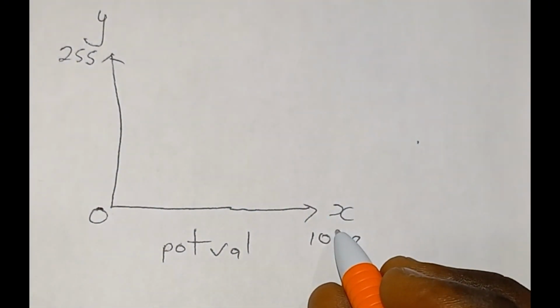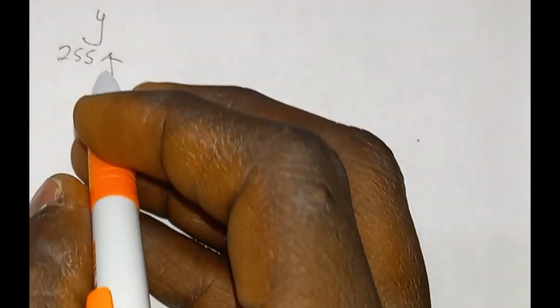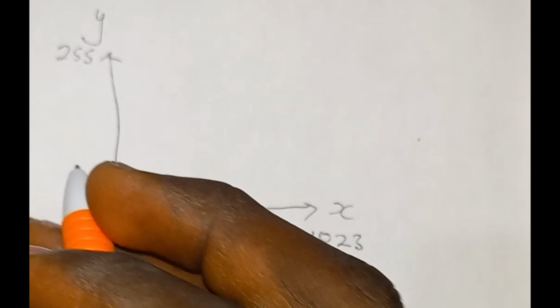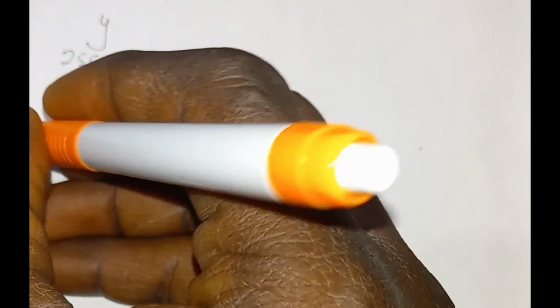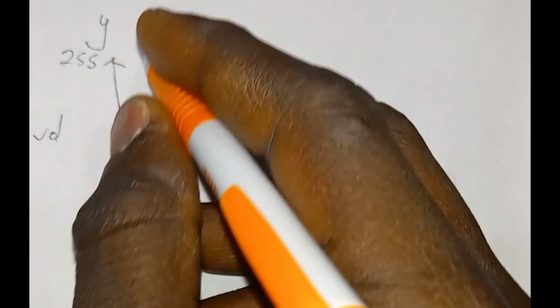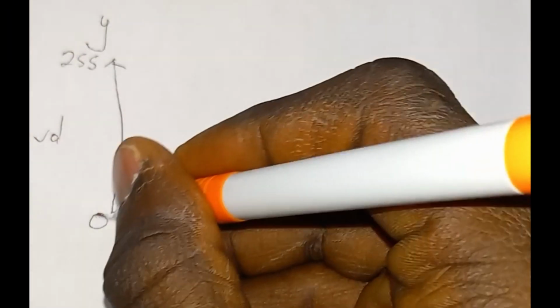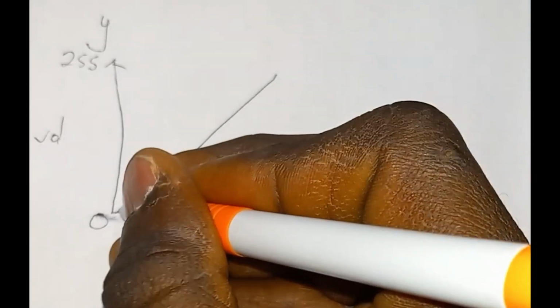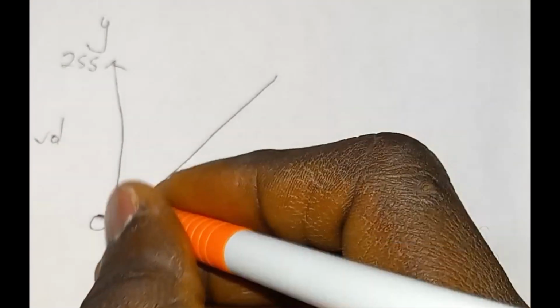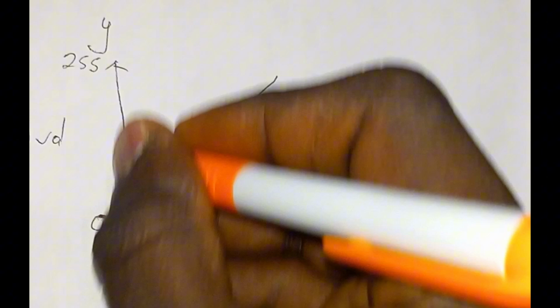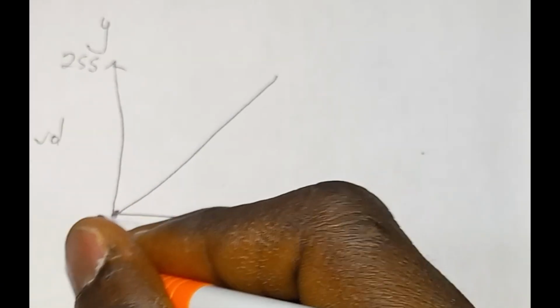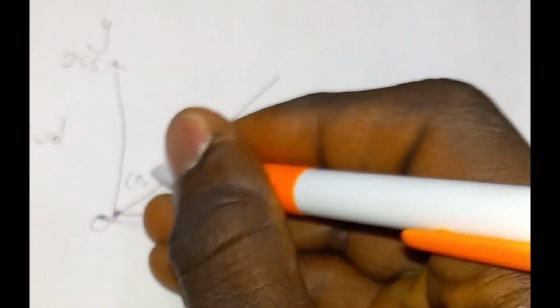So over here we're analog reading 0 to 1023. Over here we're analog writing, that's for the LED val. So then 0 to 255. If we take 2 points, first let me draw a slope. If we take a point here, we have 0 here and 0 here. So over here will be 0, 0.